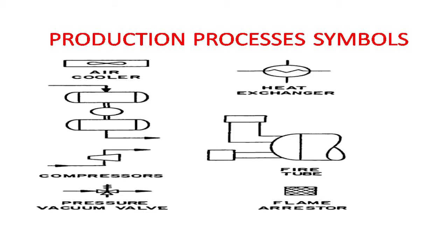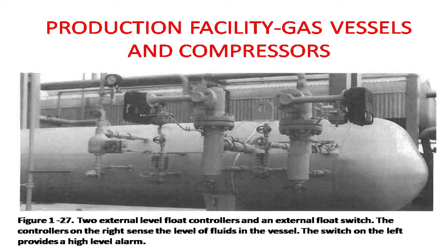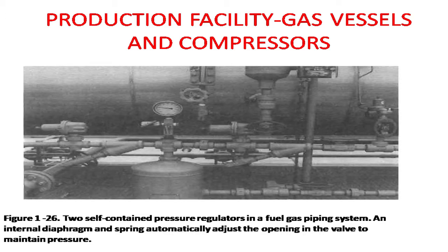Now we have flow control. It is very rare that flow must be controlled in an oil feed process. Normally, the control of pressure, level, and temperature is sufficient. Occasionally, it is necessary to assure that flow is split in a controlled manner between two process equipment, or perhaps to maintain a certain critical flow through the components. This can be a complicated control program and must be handled on an individual basis.